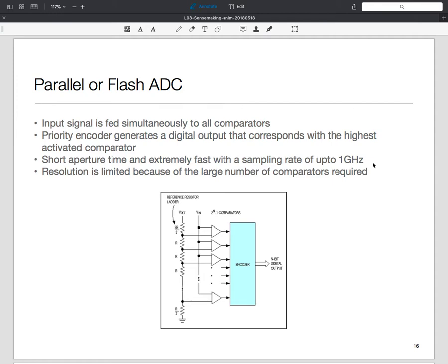So a bunch of comparators, a bunch of a reference voltage with some high quality resistors so that we have thresholds. So for example, if I have a 4-bit A to D converter, then I have 16 thresholds, so I would have 16 resistors, dividing my voltage into 16 equal levels, and I want to compare against each one of these. Now, as you might imagine, it's a fast way of doing it. It's very parallel, but it's very expensive because I have an exponential number of things.